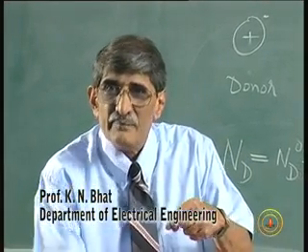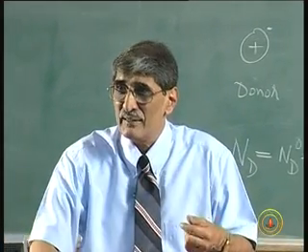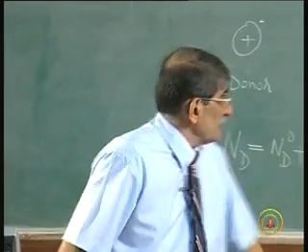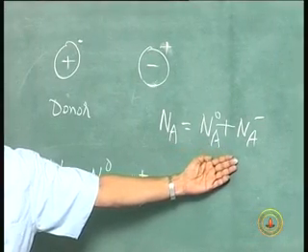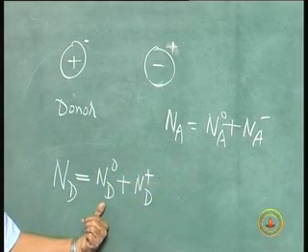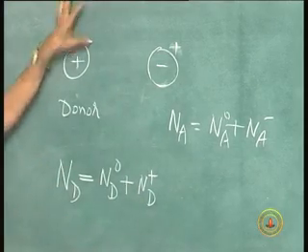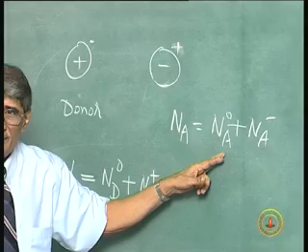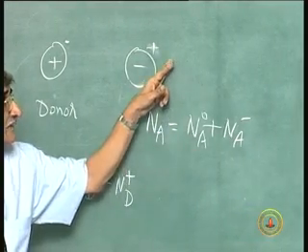That is the understanding. Okay. See, when it says ionized, what has happened at the acceptor level? An electron has gone from the valence band and occupied that position. That is the meaning of that. But the hole has been pushed down to the valence band. That is why you get Na 0 and Na minus. Okay. Not occupied is plus charge, occupied is neutral. This is unoccupied, neutral, like that.